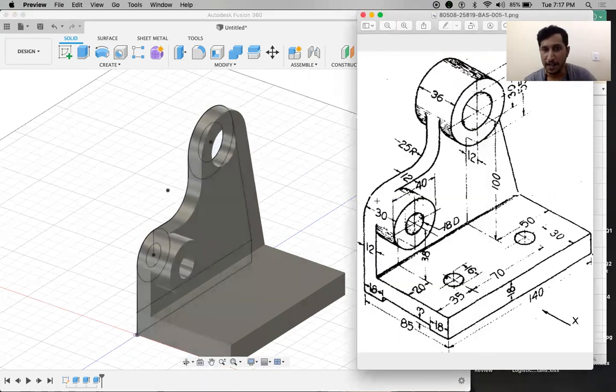But in this case, we were supposed to give thickness only towards the front. So that is 30. But you can notice this cylinder's total thickness is 36, but it is from the center. But our profile is on the rear side of this frame, right? So half of this 36 is 18, and half of this thickness is 6. So 18 minus 6 from here, this should be 12. And towards this direction, we have to provide the remaining thickness.